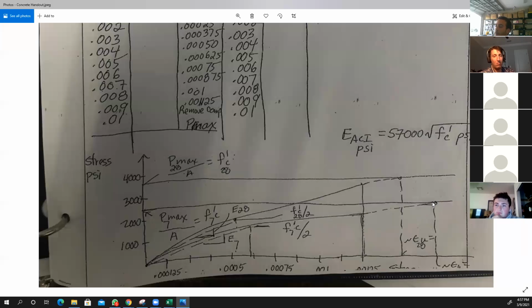But we're gonna do some manual calculations at the end, because at the end of the experiment, if you look at the videos, there are a couple of videos that I posted on Moodle already. Before the failure, we take the compressiometer out before concrete fails, because if concrete fails, that gauge is going to fail as well, but we cannot waste the gauge for each testing.